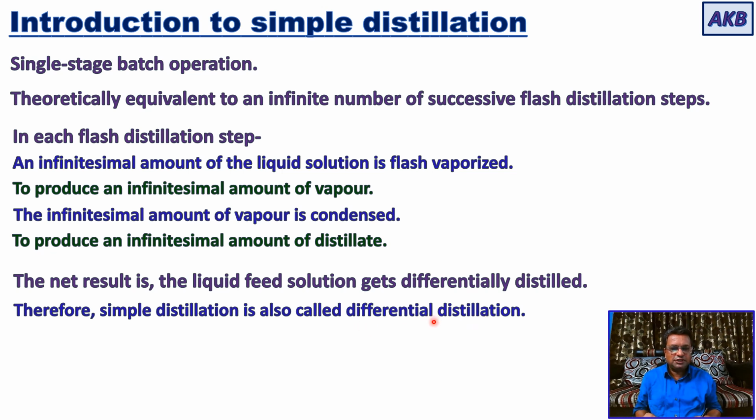Why is it differential distillation? Because in this type of distillation, the liquid solution is getting differentially distilled. Each time you have an infinitesimally small amount of liquid solution getting flash vaporized.